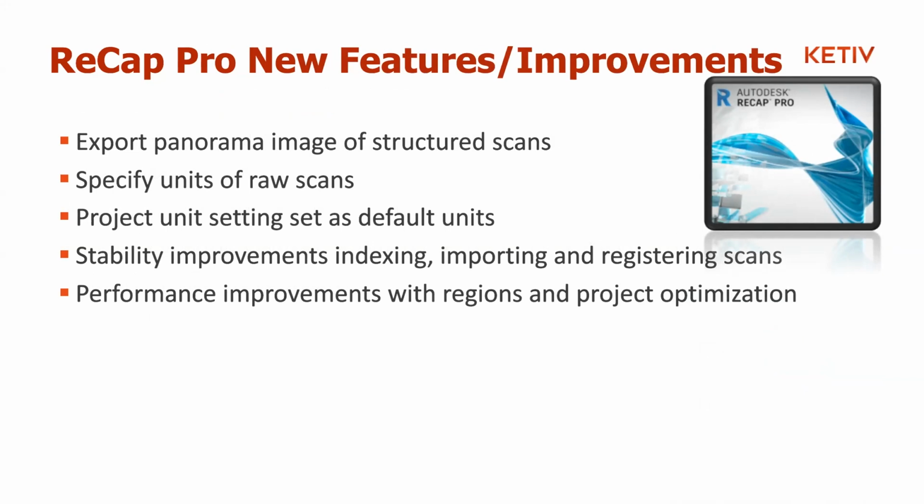If you've used ReCap in the past, you'll notice it's inherently a metric-based program. So you could create a project, define your imperial coordinate system, and then when you open your project a second time, you'd notice the units had set back to metric. You can set the units to imperial now, and it'll stick for the entire duration of the project.